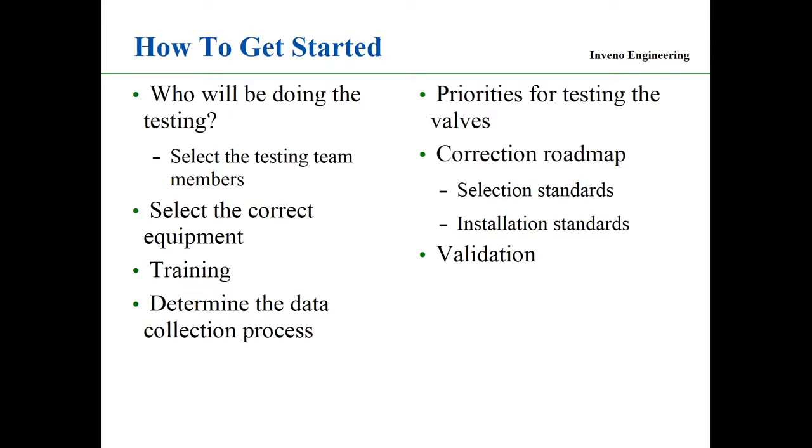How to get started? So I've got a valve out there I want to test and see if it's seated or if it's leaking through. How do I get started? Before you get started, who's going to be doing the testing? How do I select the team? Does the person have experience or doesn't have experience? Select the correct equipment, okay?